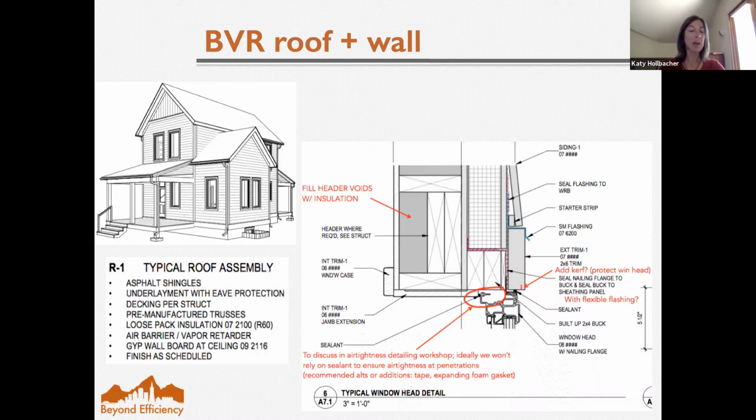I would say in our climate, the easiest thing generally is just do high solar gain everywhere, except for south exposures where maybe it really isn't possible to properly shade them in the summer, or on those just larger west expanses where the added heat gain really could be a problem. So yeah, tuning windows is a very real thing. We've done it on a number of our projects. You just need to be a little cautious.